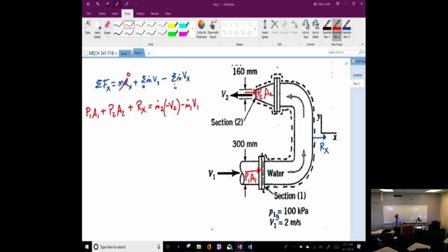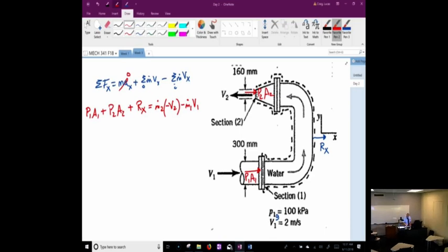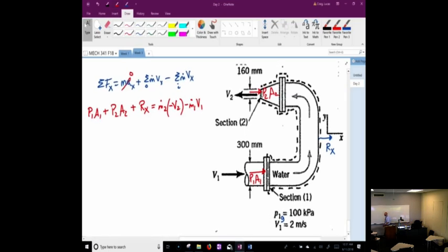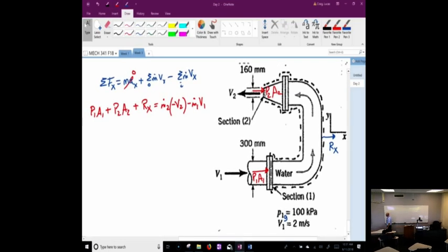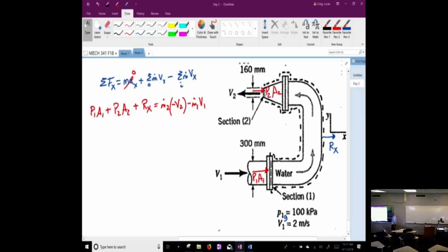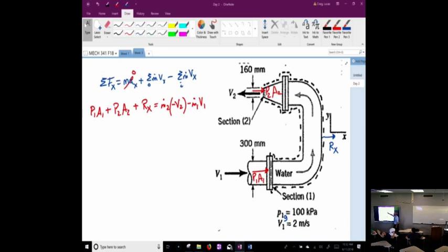What are we trying to find for it? We're trying to find that reaction force, yep. Bolting force, and then you can go ahead and size bolts or clamps, right? For machine design. So does everyone understand how you do the control volume? You label all your forces, label your velocities coming in, the states, and how we can write it in our equation. That makes sense?